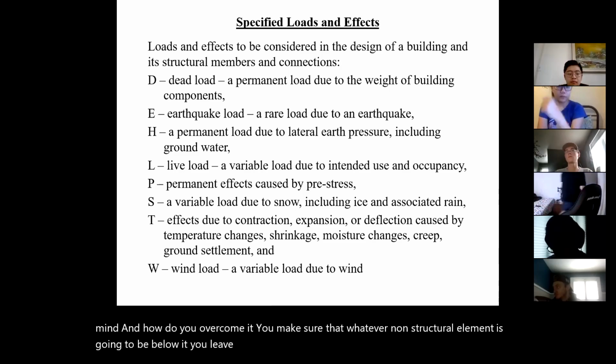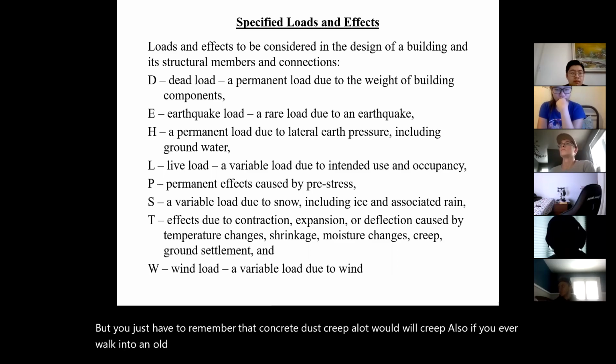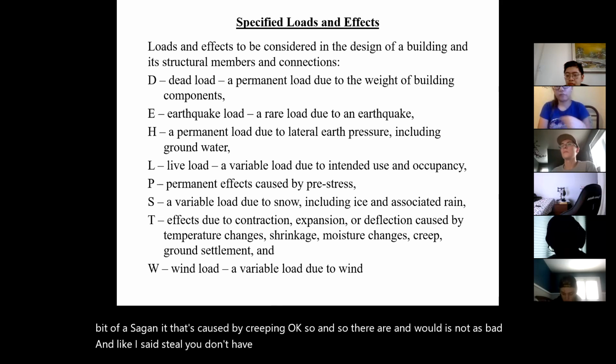There are ways of compensating for creep, but you just have to remember that concrete does creep a lot. Wood will creep also. If you ever walk into an old building and look at the floor, you see that the floor has a little bit of a sag in it. Well, that's caused by creeping. And wood is not as bad. Like I said, with steel, you don't have to worry about creep.